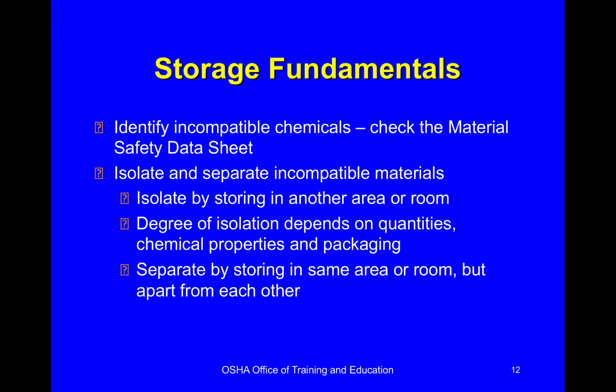So we have some storage fundamentals that we need to talk about as well. We need to identify incompatible chemicals. We want to check the material safety data sheets or the new safety data sheets. We want to isolate and separate incompatible materials. Isolate them by storing in another area or room.